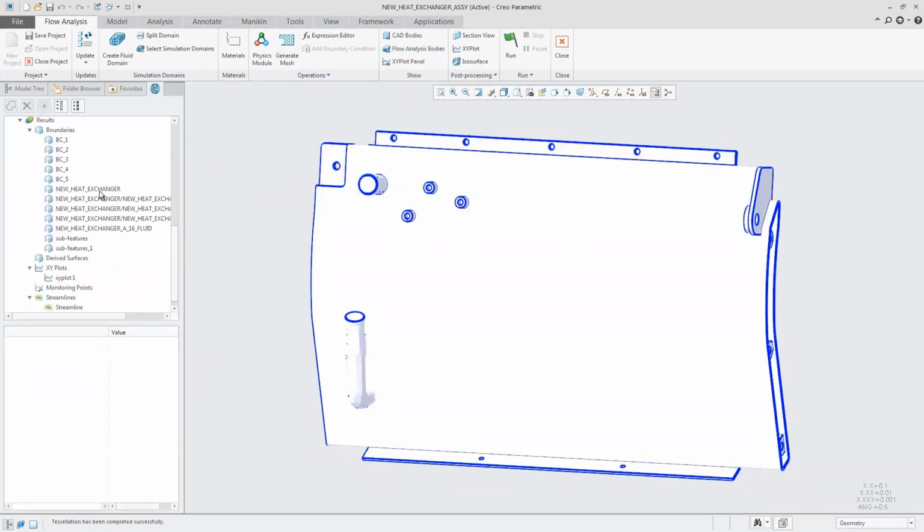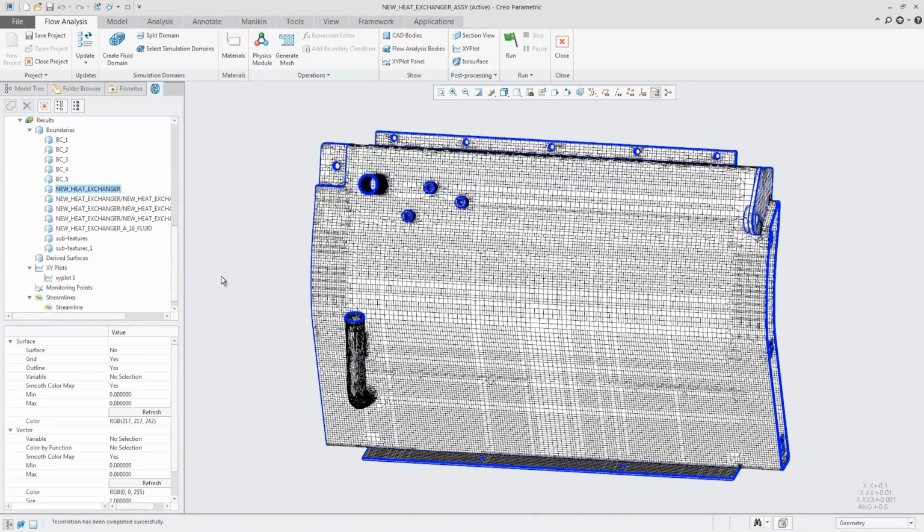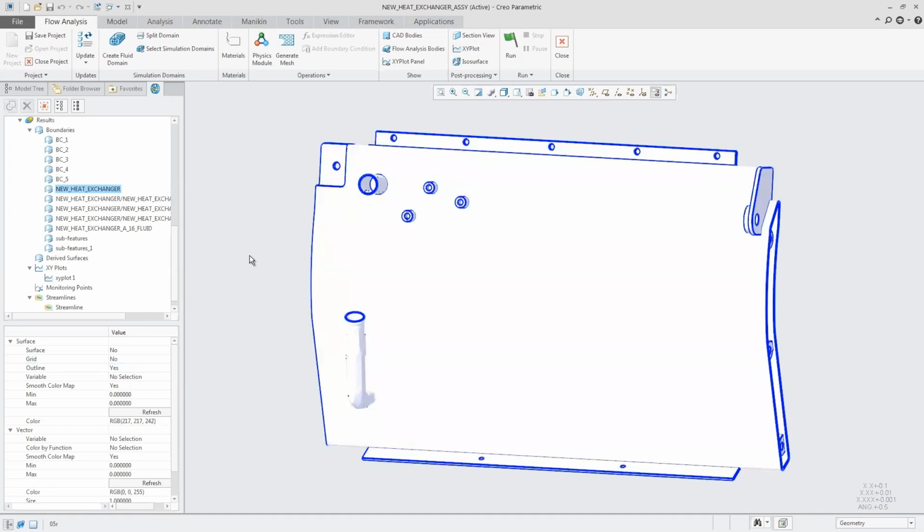And with this automatic meshing, you'll see that it uses a pretty standard way of doing this, right? So you can see in some of the areas where there's a little bit less complexity or a little bit less curvature, it's going to expand that mesh out. And then in any areas that you're particularly interested in, or any areas that might be of a little bit higher complexity, you can go ahead and make that mesh a bit finer to get better results back in those areas.